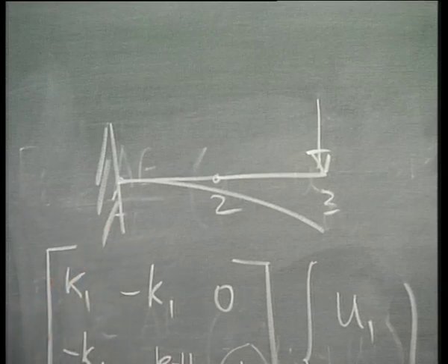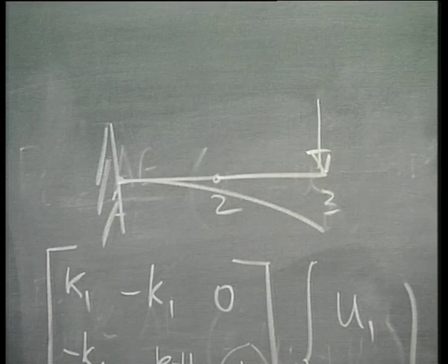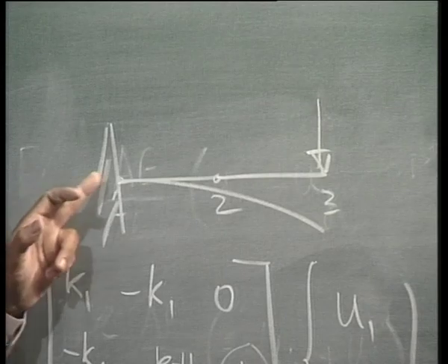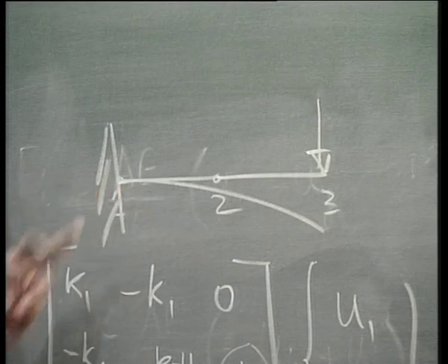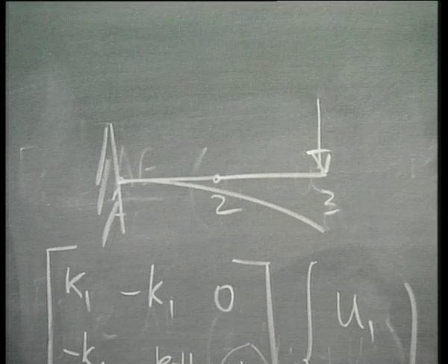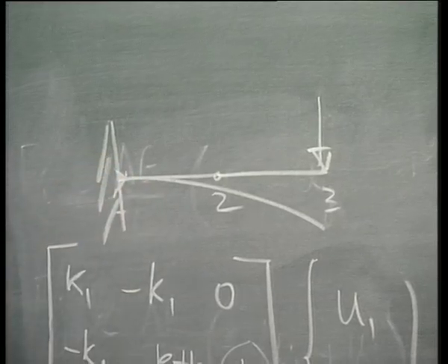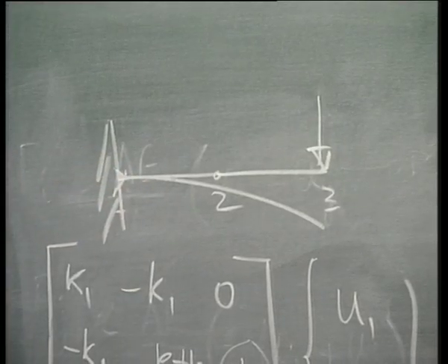In the previous case for the bar, we defined the boundary condition, there is only one. Now, we just modify the problem and ask, what are the boundary conditions? Displacement and rotation, that is right. So, displacement as well as rotation, both of them are specified at that place. In other words, the same node, the same point, is specified in a slightly different fashion, so the geometry happens to be the same.